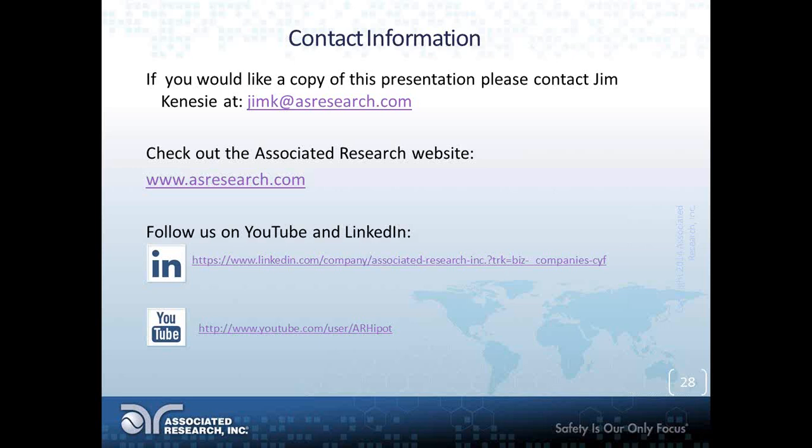And what we found is if you're Hipot testing within the spec, and I want to put an asterisk there, within the spec is very important. If your spec says you have to Hipot test this at 1240 volts, that's what we did. We did it at 1240. So within reason is basically what I'm getting at there. And we ran 10,000 Hipot tests on the same product. And then we went ahead and measured leakage current on the 10,000 tests. The leakage current on test 1 and test 10,000 were essentially the same.